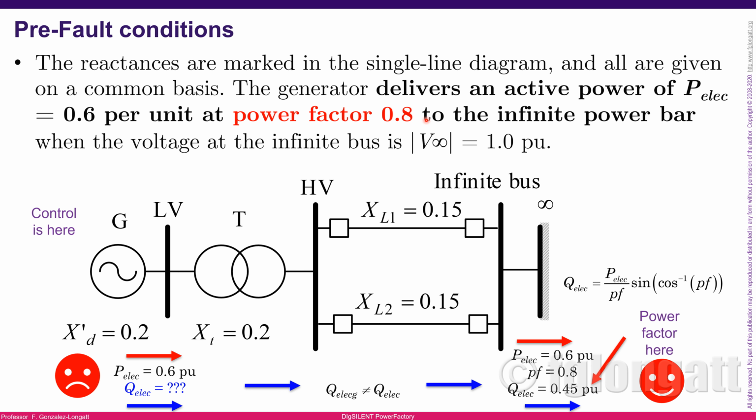What's happening if you don't care about these small lines here that say the power factor is 0.8 at the infinity bus bar, okay? What I will do is a very simple steady-state simulation inside DIgSILENT PowerFactory, and you will see the difference if you don't care about this very important step, okay? Let's go to PowerFactory and I will see you there, okay?